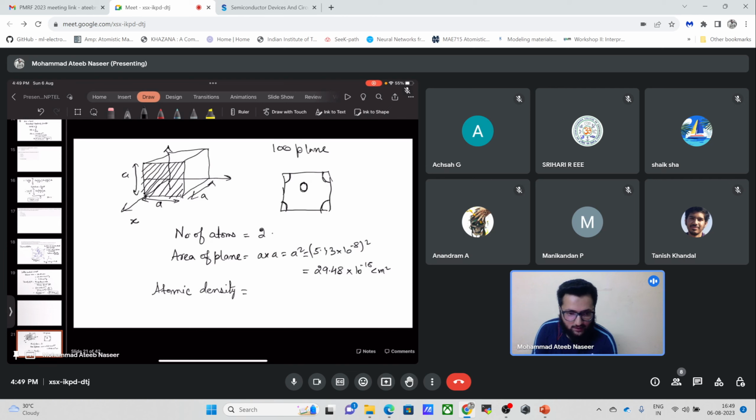So there has to be some balance between these things. This atomic plane configuration, whether we are placing it in the 100 plane, 110 plane or 111 plane, will matter for the transport characteristics, because due to the atomic arrangement in that particular direction, the properties of the material can be quite different compared to another direction.